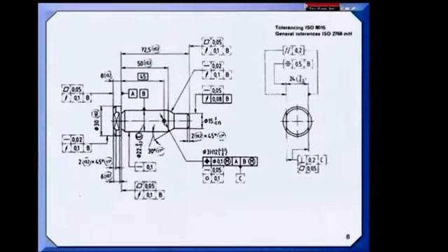This standard is an older standard, and it's going to be revised, but I strongly recommend that you just state, using Y14.5, what your requirements of your part are. Usually less than half of the features on a part require tight tolerances. Defaulting to tight general tolerances on the entire part can only increase cost.